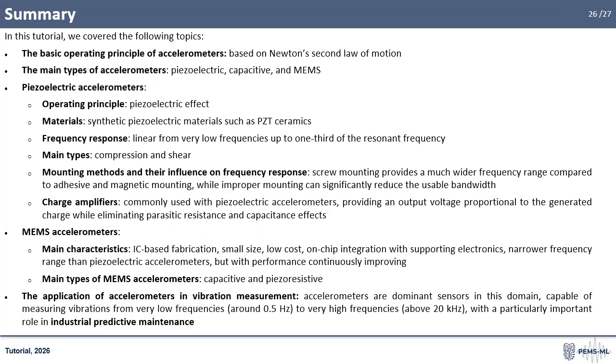In this tutorial, we covered the essential concepts related to accelerometers. We began with the basic operating principle, which is based on Newton's second law of motion, and then introduced the main types of accelerometers: piezoelectric, capacitive, and MEMS.